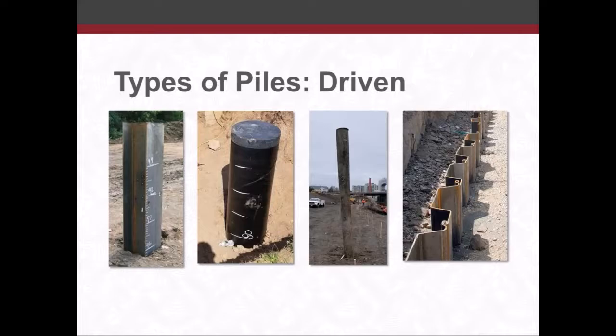Blow counts are an important aspect of monitoring driven piles. There's some older pile contractors out there that will say a driven pile is a tested pile, because if the hammer hits the pile once and the pile drops 10 feet, it's probably not going to have as much capacity as a pile that's driven to 20 blows per inch with the hammer.